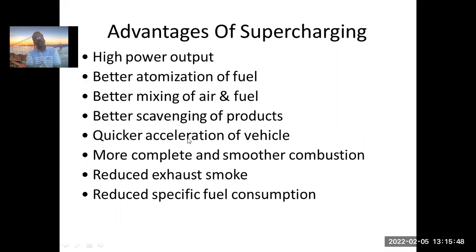See, when we discussed the carburetor, we said that when we are going for acceleration, we have to increase the quantity of air fuel mixture. In other words, we want to burn more fuel. And why are we burning more fuel? Because we want to increase the power. So what is the requirement for acceleration? More power. And what are we going to get when we are supercharging? We are getting more power. Correct? So when we are using a supercharger, we are going to get quick acceleration, better acceleration.